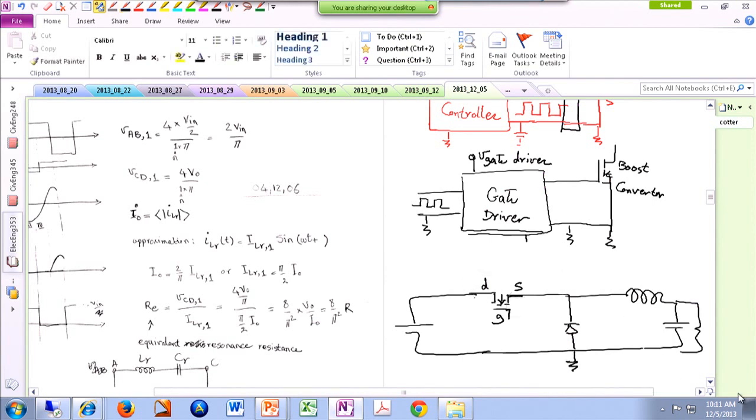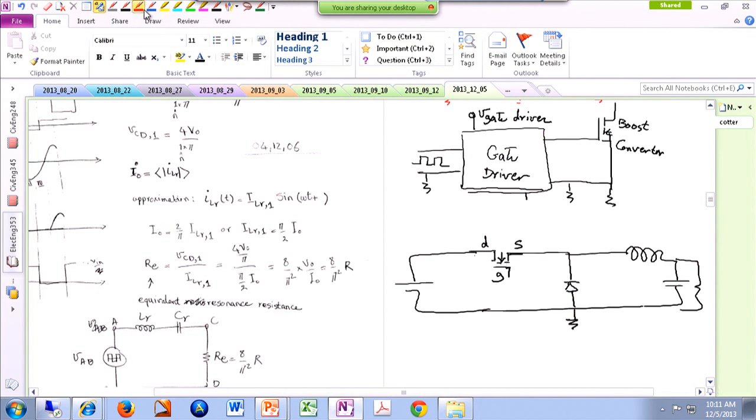So technically what happens is, remember, this cap that you have to charge and discharge exists between the gate and the source of your transistor. So your gate driver should also be connected to those two pins. So if I have this gate driver over here, okay, one pin goes here, the other pin goes here, and the gate driver has its own VG, or its own power supply, with respect to another pin.